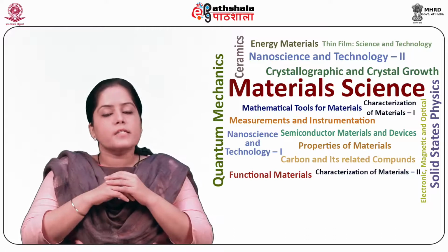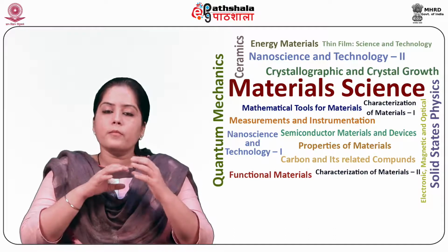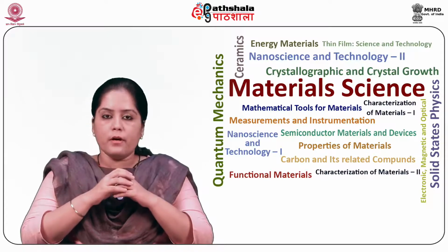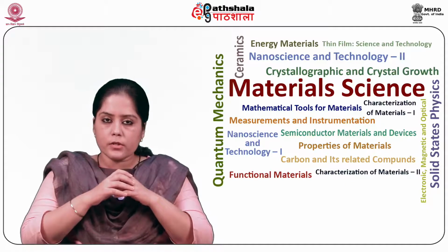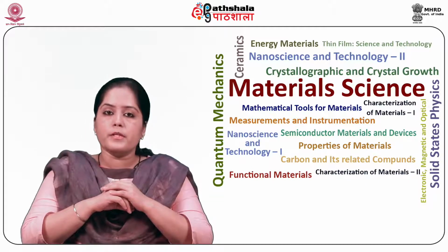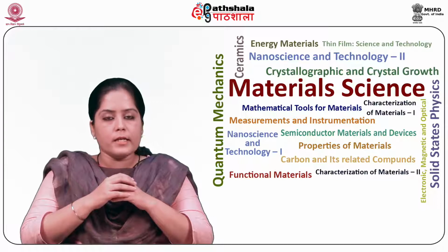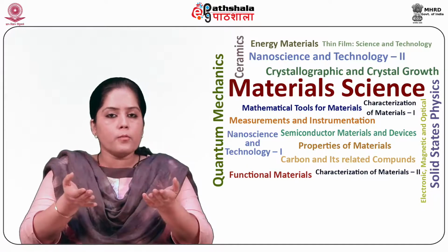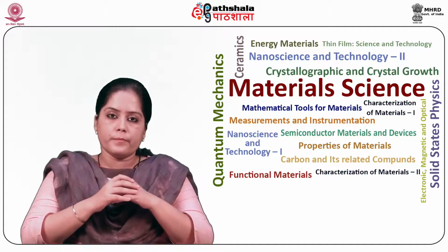Third is tetraethyl orthosilicate with conformal step coverage or void-free good step coverage. Next, it is used for silicon carbide deposition. It is also used for diamond-like carbon deposition. Advantages of this technique are low operating temperature, uniform coating of different shapes, good step coverage.